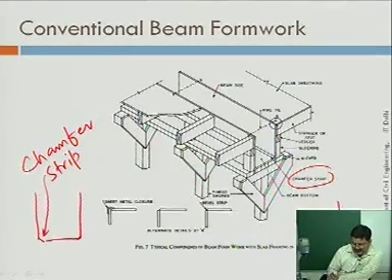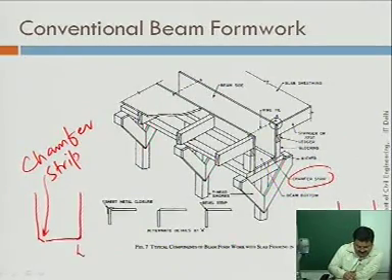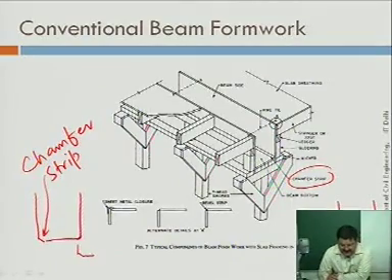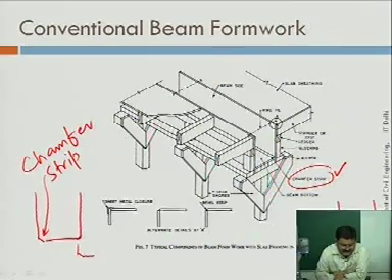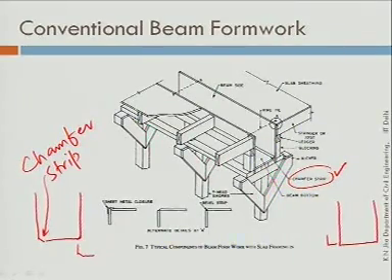So, this is in contrast to an arrangement like this. In this case the edge is sharp, here the edge is something like this. So, you can add one more member called chamfer strip, right. Rest of the things are same. Sometimes you connect these two sides of the beams with wire tie. So, these are your wire tie. Okay. So, this component could again be separate.